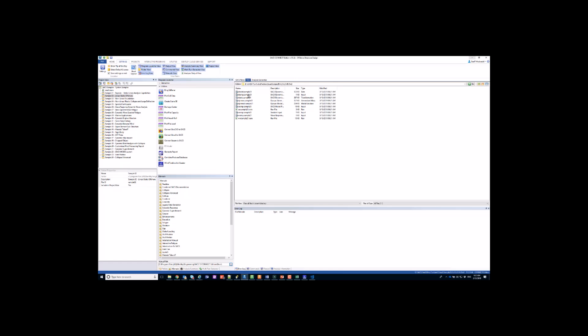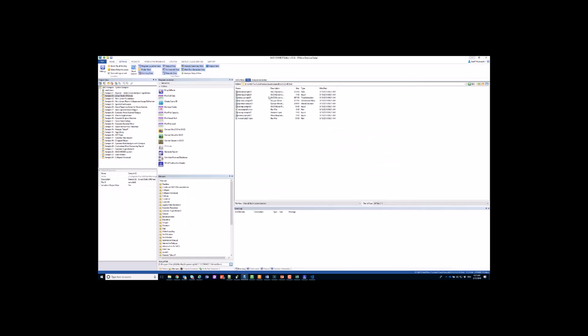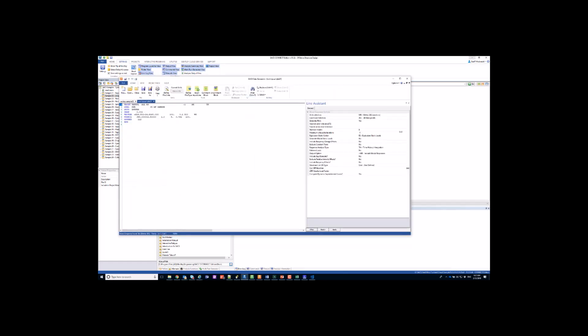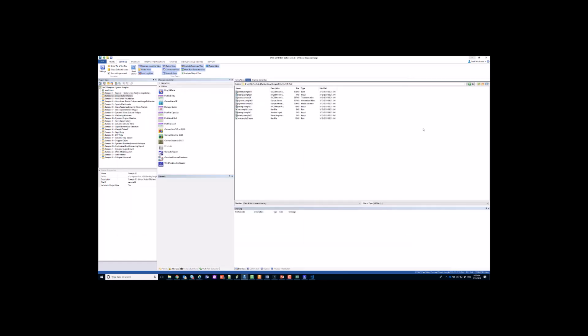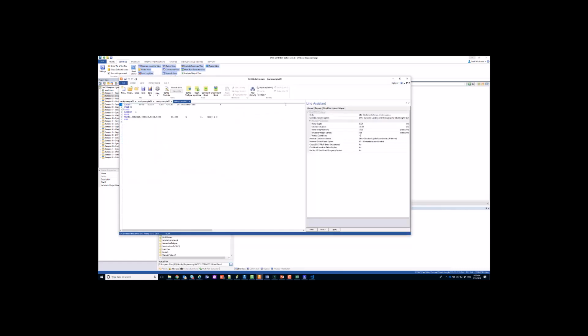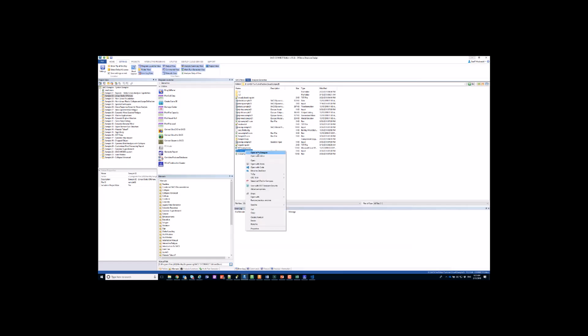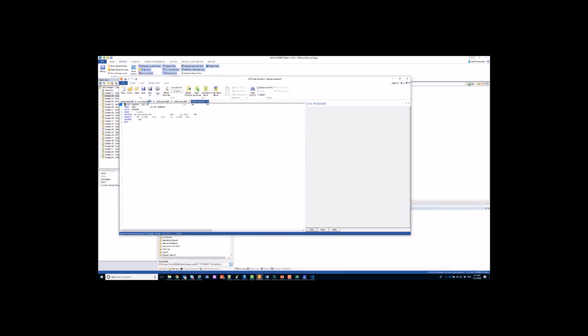So we can see here, okay, so the partial input files that we're going to be modifying are the wave response input file, the dynamic superelement input file, and I believe it's the C-state input file here. And just as an example, we can go back up to the top and I can show you what the original input looked like, so we can see how it's been modified. I'll do that with the wave response input file and the dynamic superelement input file.